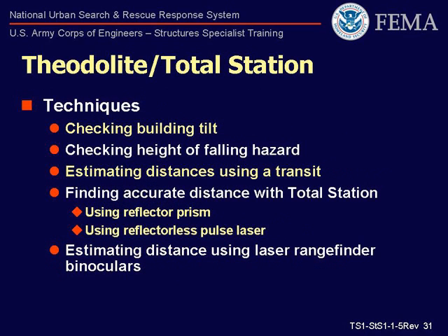Several techniques of displacement monitoring are possible on a rescue event site. These could include checking building tilt, checking height of falling hazard, estimating distances using a transit, finding accurate distance with total station, using reflector prism, using reflectorless pulse laser, estimating distance using laser rangefinder binoculars.